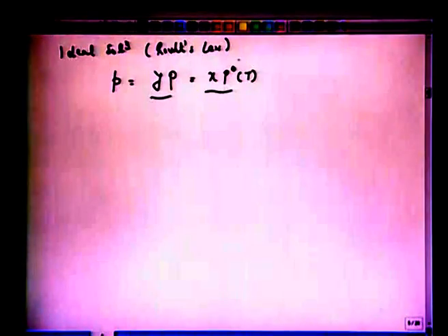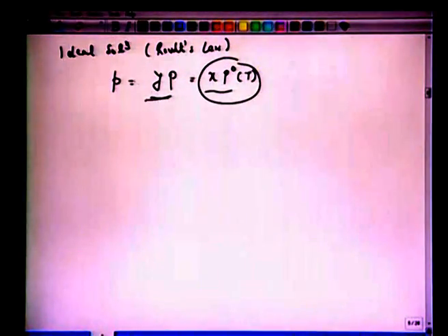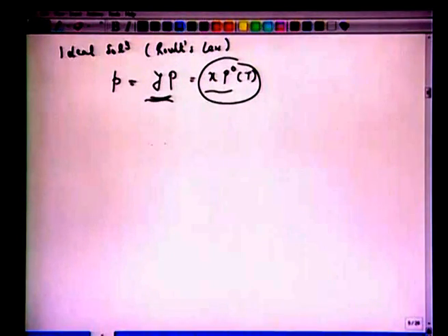And then knowing the total pressure, we can calculate this Y versus X curve. So let's write down here that we are assuming ideal solution and we are applying Raoult's law, which is Yp equals X P0. So see the difference, partial pressure equated in two phases. So this is Raoult's law and we have equated it with this Y to P, partial pressure, Dalton's law, you can call it. Okay, so vapor pressure at this temperature of 26 degrees centigrade, we can go back and